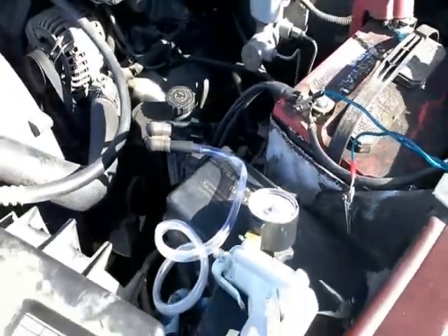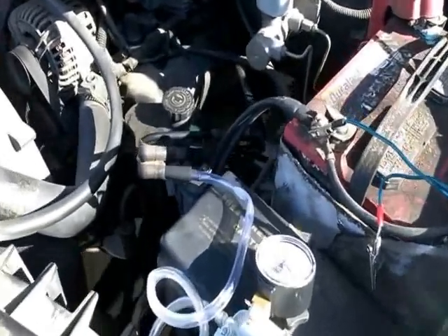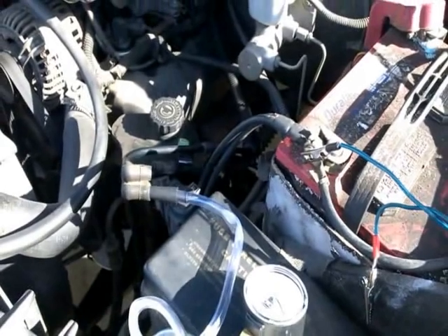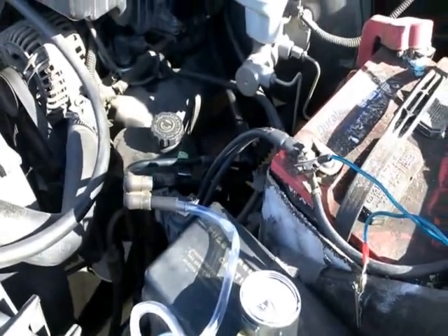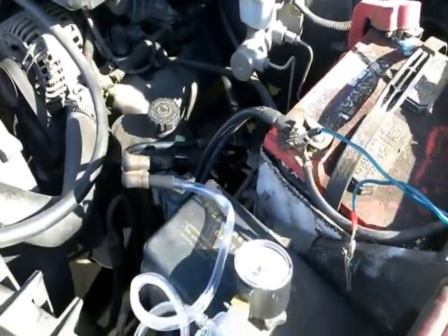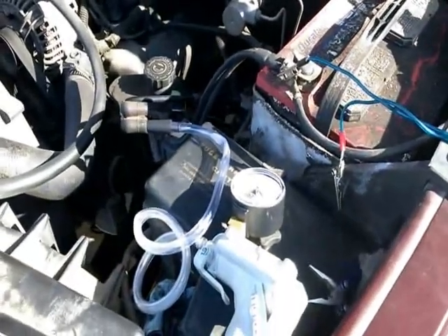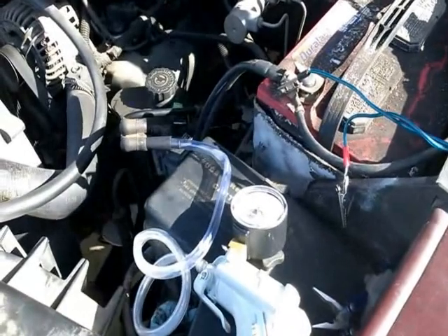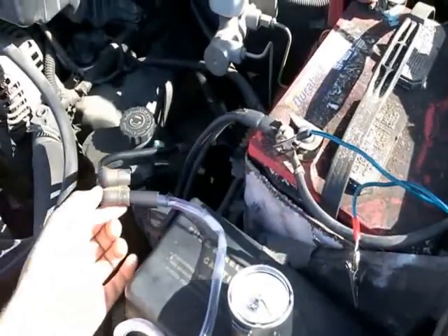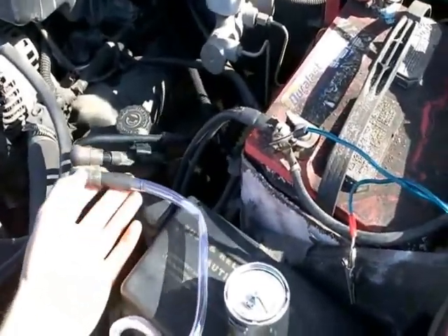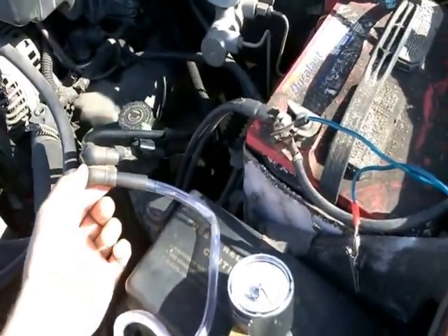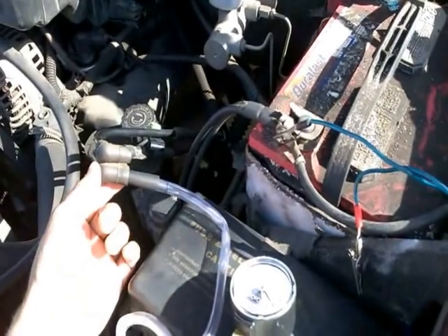All right. The easiest way to test this natural vacuum leak detector switch slash solenoid vent valve is to use a vacuum pump and a voltmeter. On the vacuum pump, you need to attach the adapter to the bottom canister hose, which routes all the way into the evap canister.